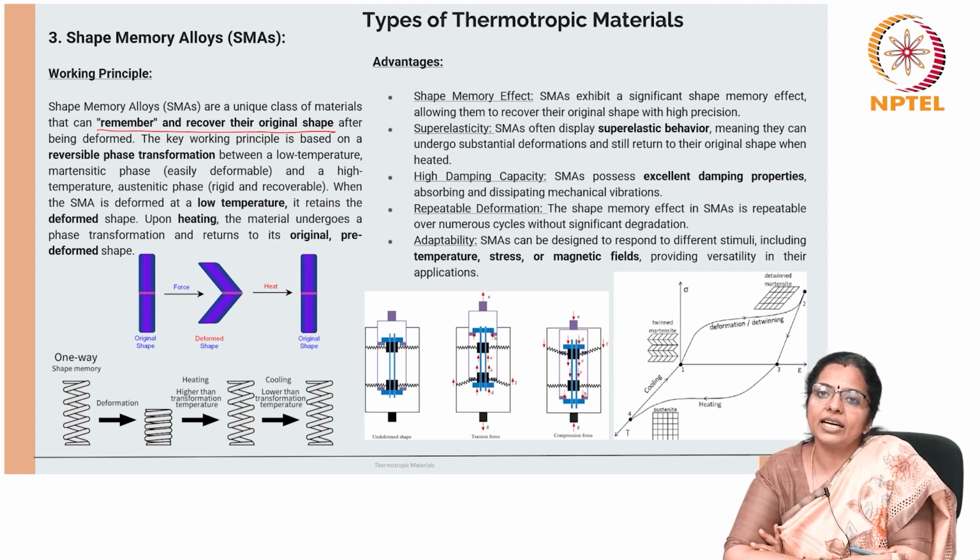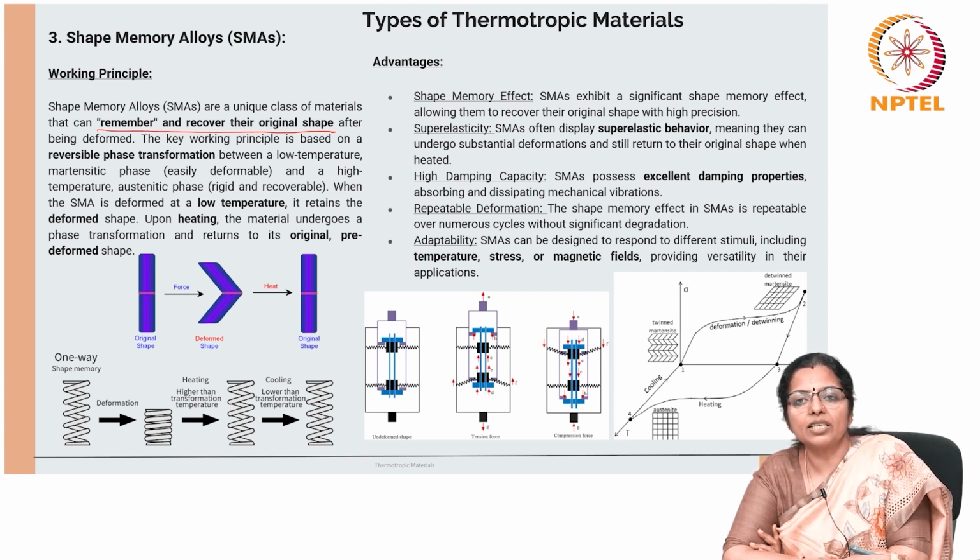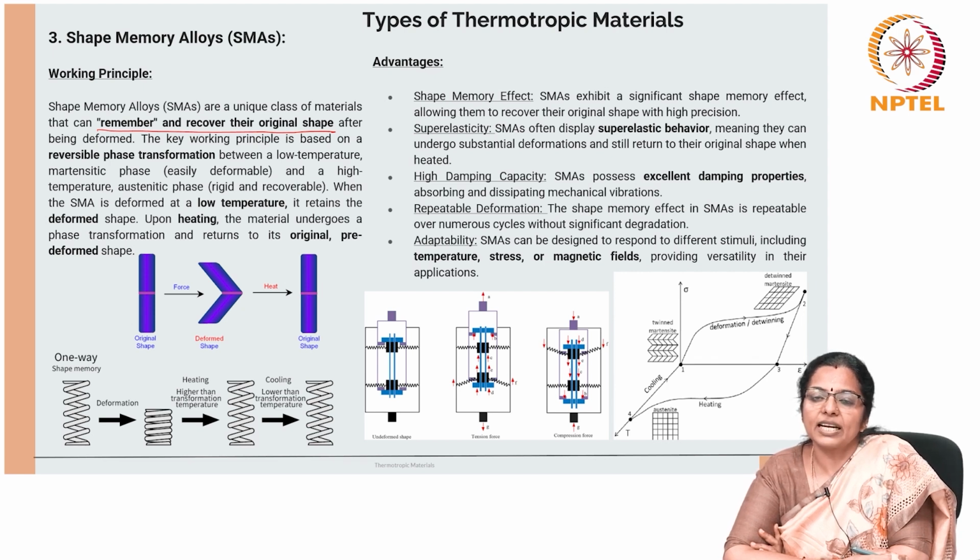They have high damping capacities. SMAs possess excellent damping properties, absorbing and dissipating mechanical vibrations. They have repeatable deformation. The shape memory effect in SMAs is repeatable over numerous cycles without significant degradation.